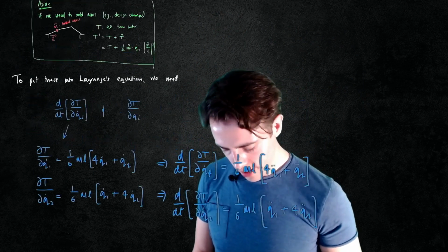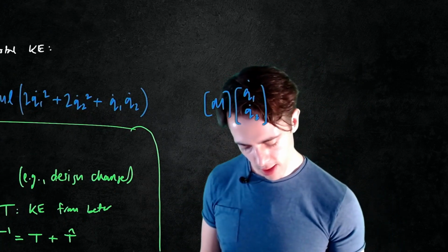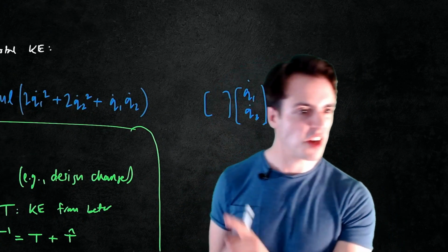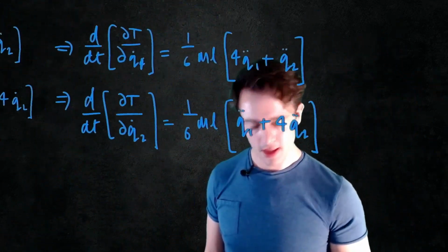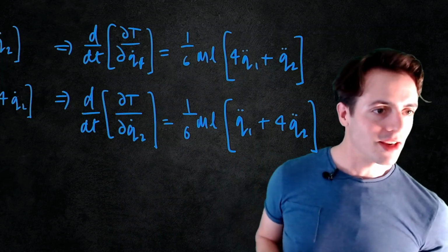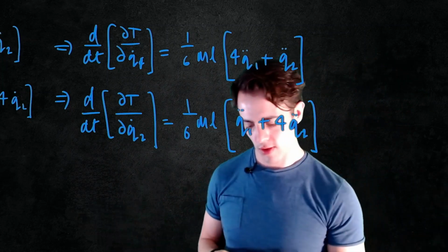Okay, I just spoke a little bit too soon up here when I called this the mass matrix. This wouldn't be the mass matrix; I could have some matrix in here. The mass matrix is actually going to be when we have double dots in here, because that then gives us a mass and an acceleration, which gives us inertial forces.